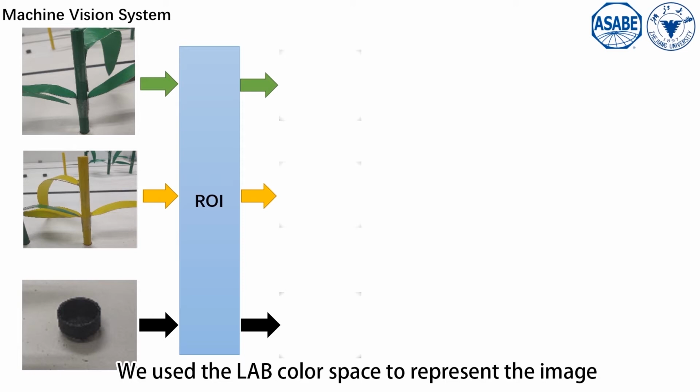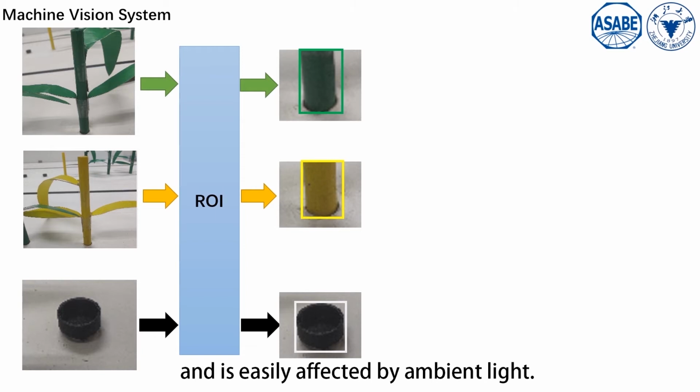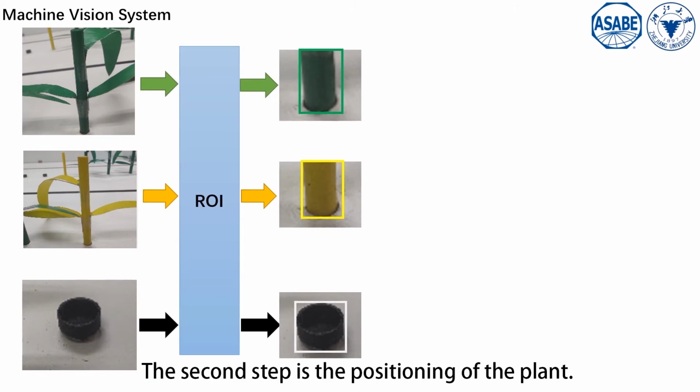We used a Lab color space to represent the image and set an appropriate threshold for 3 channels. However, the disadvantage of this method is that it is not robust enough and is easily affected by ambient light. In order to solve this problem, we designed a light system to maintain the stability of the light intensity by external LEDs. The second step is the positioning of the plant.